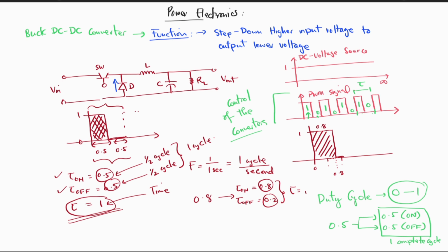In this case, you can see that the period for both the T on and T off changed. However, the period of the waveform is still constant. Imagine if we change the frequency of the PWM signal. Now it will affect the fundamental period of the waveform. However, the T on and the T off will vary based on the duty cycle. And this duty cycle is responsible for controlling the PWM signal, and in that case, it will control the T off and the T on period of the PWM signal, which is known as the pulse width modulation signal.